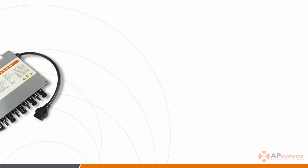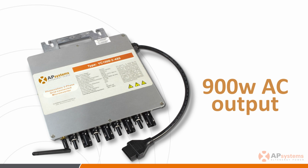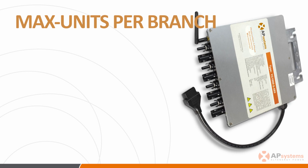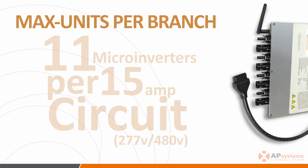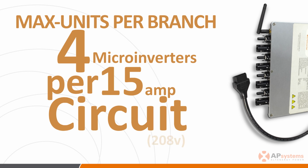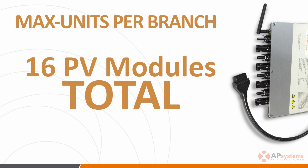The total rated continuous output power of the YC1000 is 900 watts AC. The maximum number of units per 277/480 volt 15 amp 3-pole breaker is 11, or a maximum total of 44 PV modules, and the maximum number of units per 208 volt 15 amp 3-pole breaker is 4, or a maximum total of 16 PV modules.